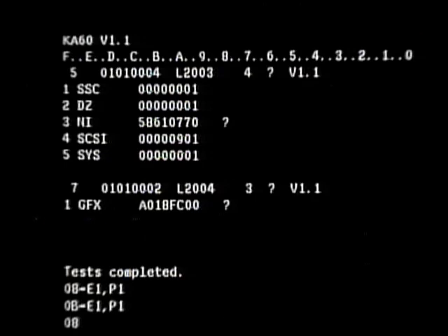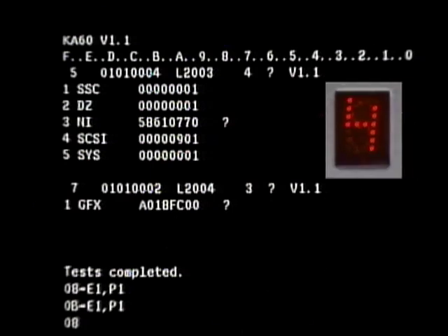Once this initial check is done, the countdown is displayed on the console terminal as well as the LED display on the I/O cover. If an error is encountered from this point on, the individual test that failed will be aborted and the diagnostic will continue on with the next test. After the PST string has completed, any errors will be displayed on the console terminal, and the physical slot number of the failing module or subsystem will be displayed in the LED display on the I/O cover module.